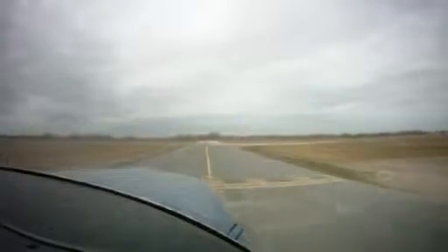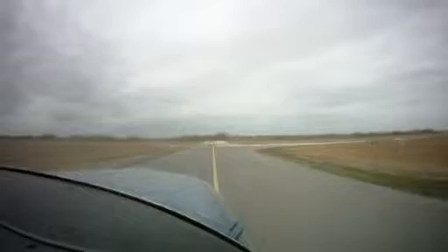Okay, my friends, today we are going to practice a crosswind landing and takeoff here on the airport of Edinburgh. And that involves a specific technique to perform before we take off or before we land. The first thing that I want to do is align myself with the runway. So I'm going to go ahead here. Airport traffic November 65328, position and hold runway 32 Edinburgh. So I've already advertised my intentions to everyone around here.